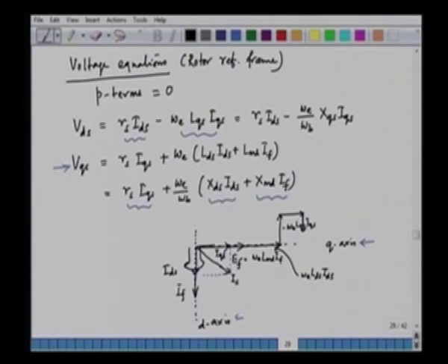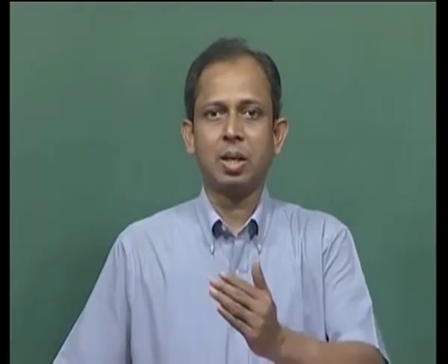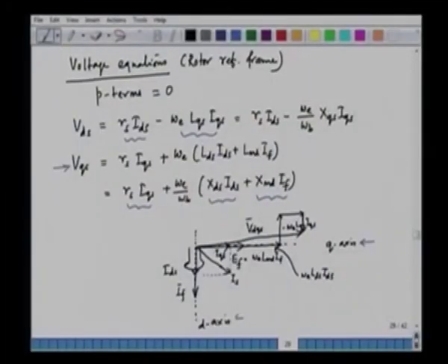And the resultant voltage would be somewhere here. So this is VDQS, this is also a phasor. So we have been able to write the equation in the d axis and the q axis. We have two algebraic equations, and we separated these two equations and we added the phasor in the q axis, in the d axis, and we could draw the final space vector or the phasor of the voltage VDQS. The VDQS is a phasor of the voltage applied to the stator of the synchronous motor.